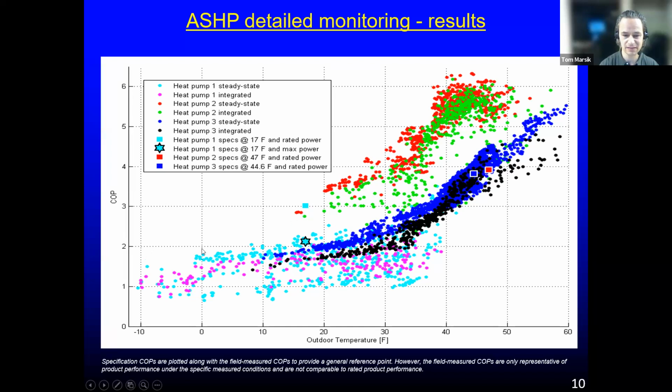Now, looking here, we can see the coefficient of performance is close to 1 actually. It's typically not an appropriate situation to use a heat pump. And remember, in a typical rural Alaska community, which uses diesel for electricity generation in the diesel generator, and also diesel for heating buildings, I explained that we need a COP of at least about 2.5. So here, we are way below 2.5 with this operation as a heat pump in this region. So here, the amount of diesel that the power plant is burning to produce the electricity for the heat pump is greater than if you were just heating the building with diesel in an oil-fired heating system.